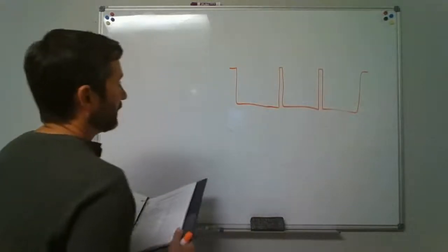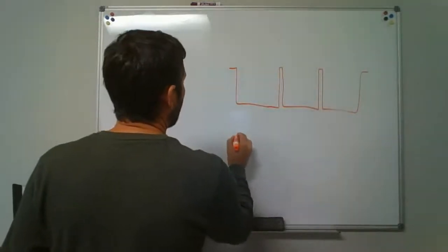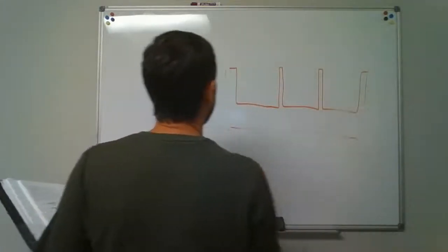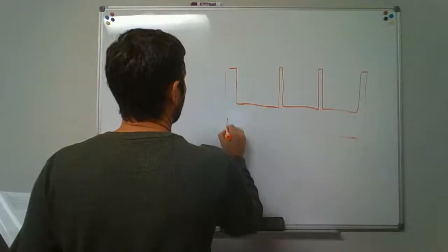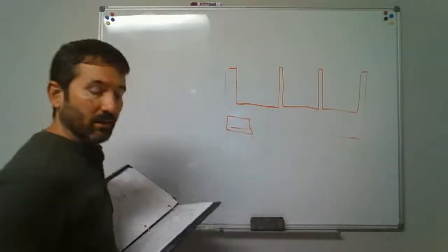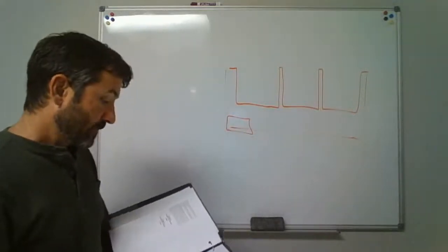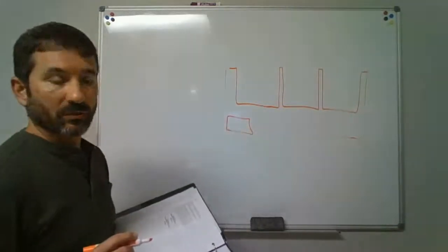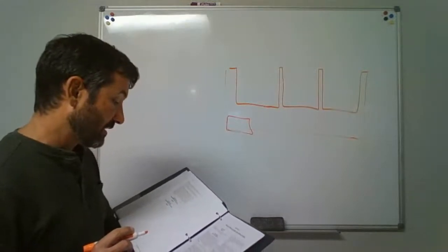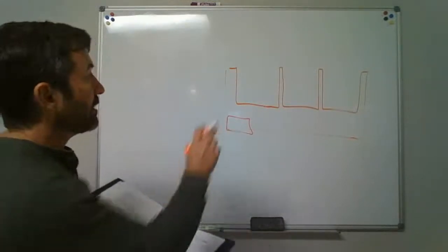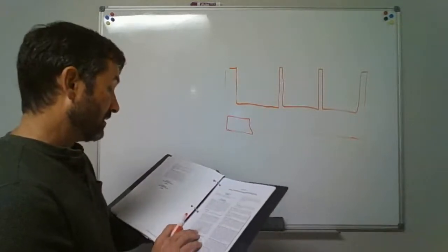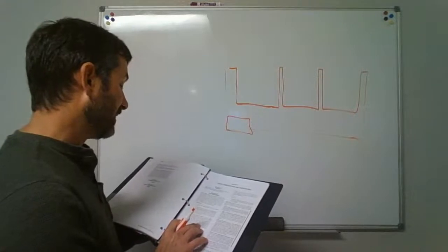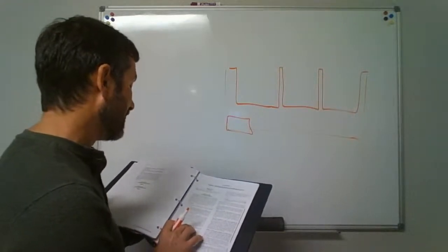Okay, anyway, and then on the cabinet or this shelf underneath this big stainless steel sink thing that they have here, maybe we have a grease interceptor there. Okay, and they said in the design this is allowed to be. This interceptor is going to be serving as the fixture trap, and it says it can do that. It says not more than a 3-compartment sink, okay, where the vertical distance from the fixture outlet to the inlet of the interceptor does not exceed 30 inches.